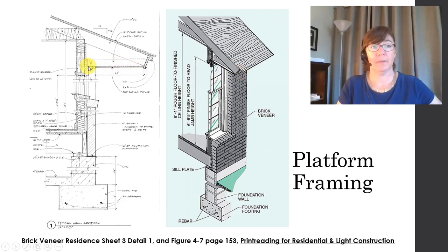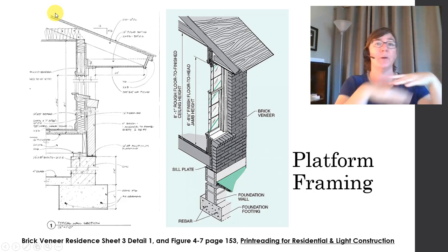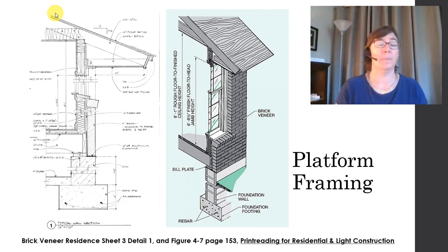And this piece is the soffit. If you'll remember in the vocabulary section, we couldn't see the soffit. This piece under the eave is the soffit. Here's our fascia right here. And on top of our roof rafters right here is the roof sheathing. This is a plywood sheathing. And on top of that sheathing would go the roofing felt or waterproof membrane and whatever roofing material, maybe shingles, that's not shown in this picture. So in our three-dimensional view, what we're seeing is that plywood sheathing right here.